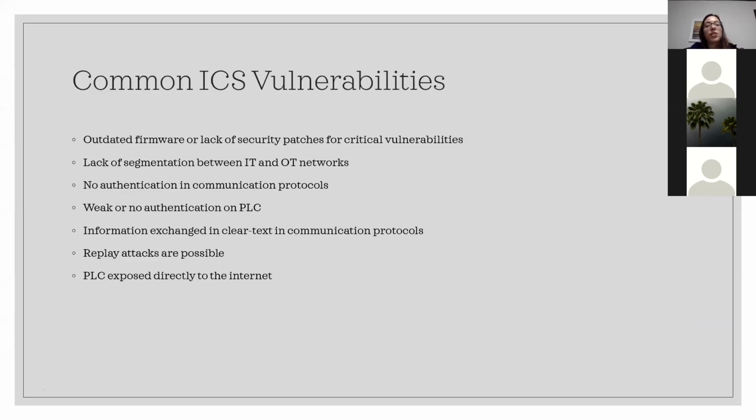So we've already touched on a couple of these, but here are some of the most common ICS vulnerabilities. We talked about how there's no authentication in most communication protocols for ICS. Also, very little information is encrypted. The communication protocols I'm familiar with exchange everything in clear text.